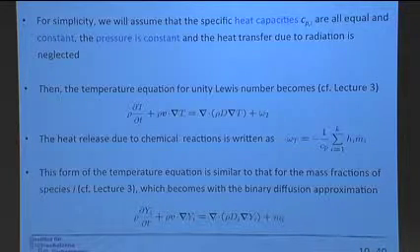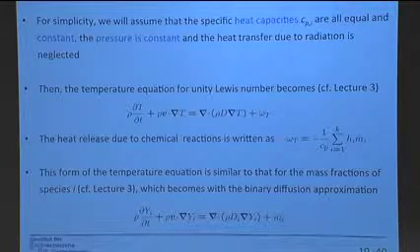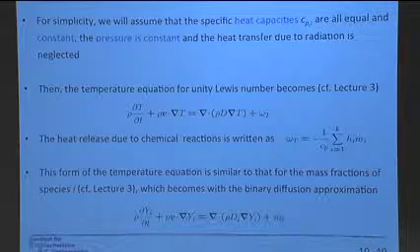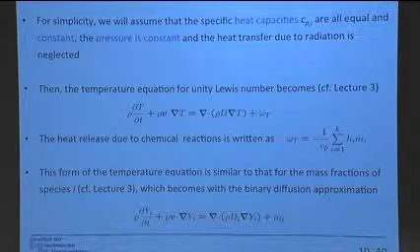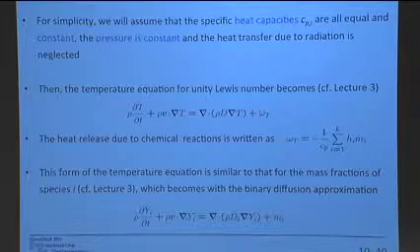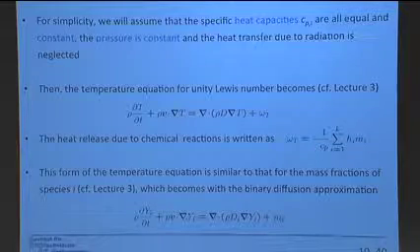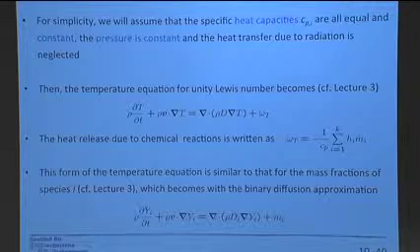these are the balance equations for the reactive scalars. Just like earlier, we derived equations for the mean momentum or mean velocities. We can also derive equations for the mean, the averages of the scalars. And then again there's a nonlinear term here. We get a transport term from this. That's the so-called scalar flux term. It's just the turbulent transport term for the scalar. We'll see that on the next page.